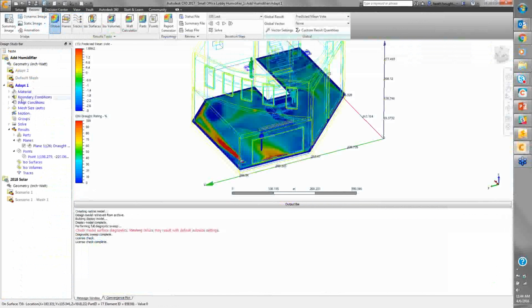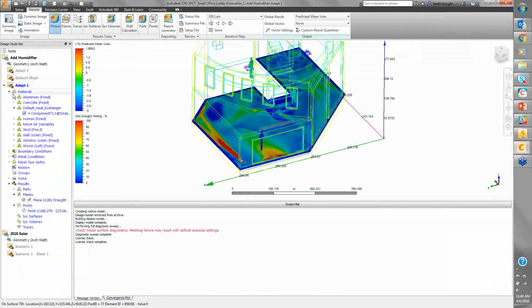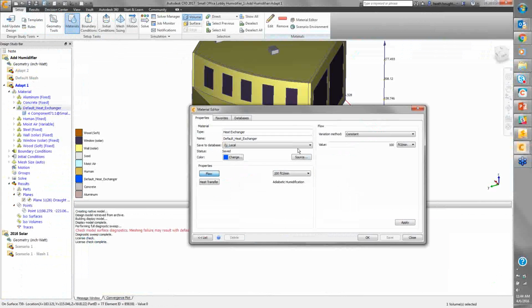One of the things we added, and I'll just barely go across it, is heat exchanger. In the past, if you turned on humidity and you had a heat exchanger, they weren't compatible. Now they're compatible, but more importantly, in the type of things they can handle is not only the 4 that were there before, heat input extraction, temperature change, heat exchanger, or air conditioning. You now have these humidification and dehumidification processes that could be part of the heat exchanger.